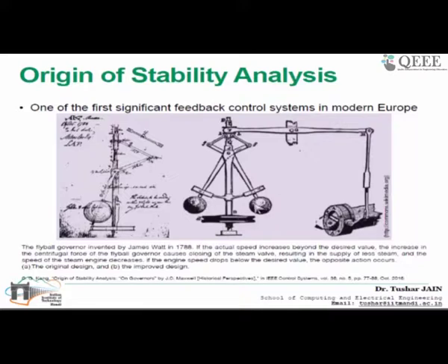The very basic function of this governor is that when this disk D starts rotating, these 2 balls start moving apart from each other. Whenever they start expanding, this pulley will be pulled down, and in turn this pulley will turn up, and then finally it closes this valve. So this is basically a control as well. Now, how is it used to control the flow of the fuel?